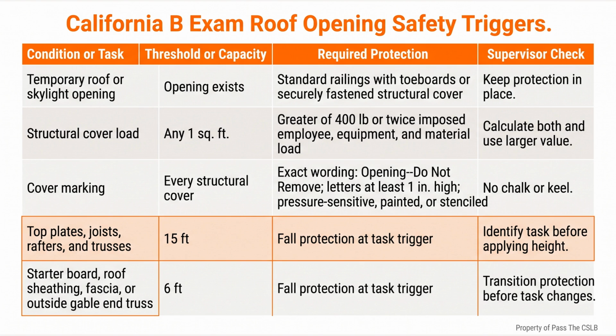A missed condition often appears only after roofing, drywall, or finish work hides the area. The result can be removal, redesign, inspection delay, damaged weatherproofing, and trade disputes. A disciplined pre-cover check prevents that chain of rework. If field conditions force a change, I do not let an oral shortcut become the new structural detail. I route the change through the approved design and inspection process required for the project.